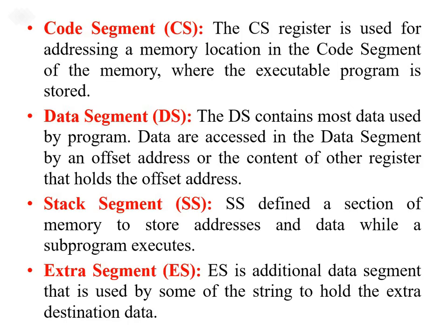Data segment. The data segment contains most of the data used by the program. The data in the data segment is accessed by an offset address or the content of another register that holds the offset address. So in this data segment, we are storing the offset address or the content of other registers. Next is the stack segment.